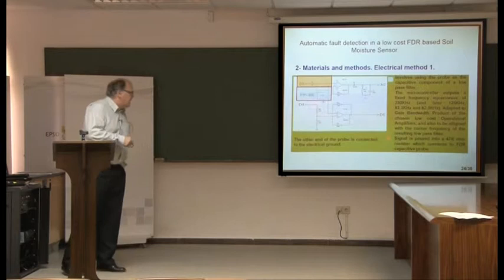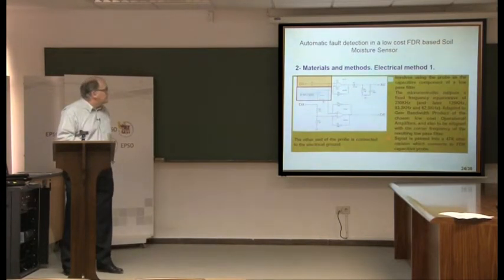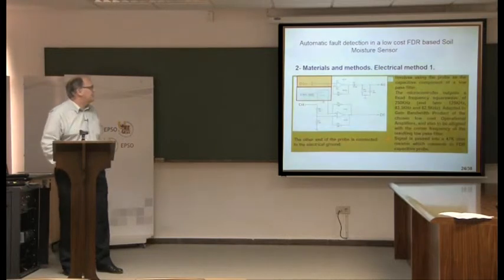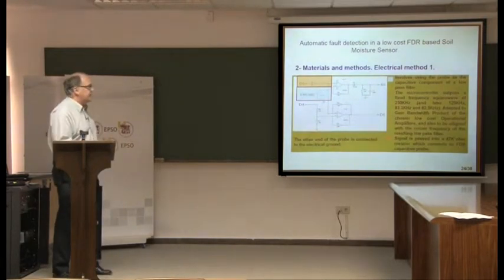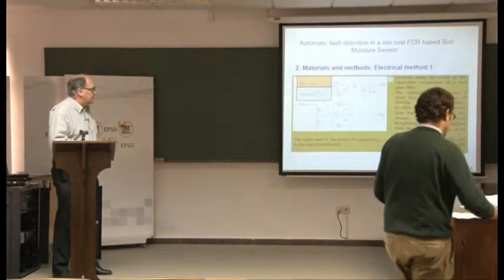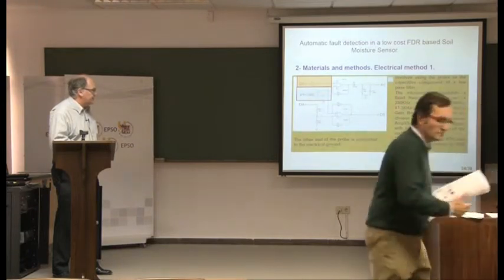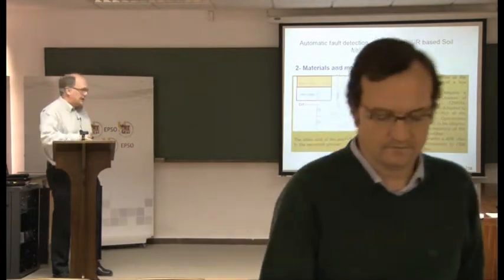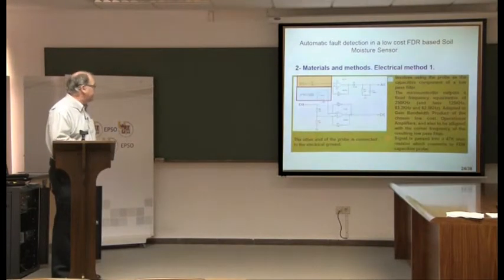This is part of the circuit of the probe electronics. Here the probe is represented by this capacitor, and it's fed by a signal generated here on input D3. In this first technique, we use the probe as the capacitive component of a low-pass filter. Those of you with an electronics background will recognize a classic RC arrangement. We pass a signal into the probe at a fixed frequency. We've used 250 kilohertz and 125, 83 and 62 kilohertz and recorded the values that we got through.